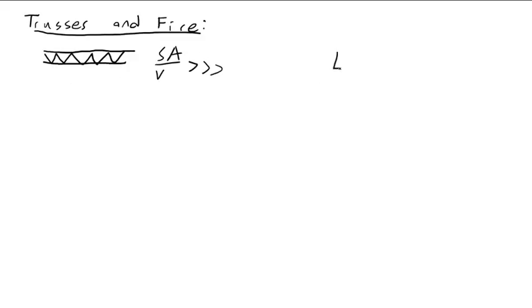A big wooden beam, however, would need to be pretty hefty to carry the same load. You'd end up with a big old cross section to carry the same load as a steel truss. However, if there's a fire below this thing, yes, it's going to end up pretty scorched. But if you have a 2-foot by 3-foot wooden beam, especially treated material, it's going to take a long time in a fire before it actually burns all the way through.